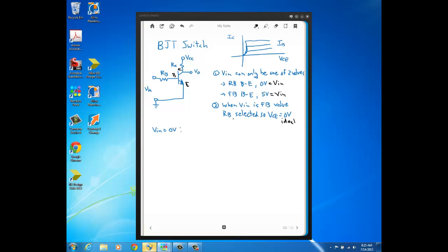It involves what's called a load line analysis. But in a non-major class like this, what I do expect you to know, based on previous discussion, is that you should understand that the value of this resistor in the base region affects what the voltage from the collector to emitter is over here on the output side of this circuit. And that's because we talked about how a BJT is a current control device, where you're controlling a current over at the collector side with a current on the base side.